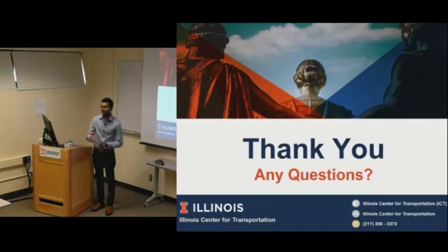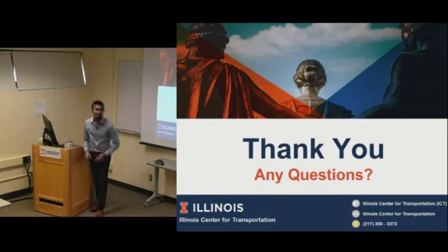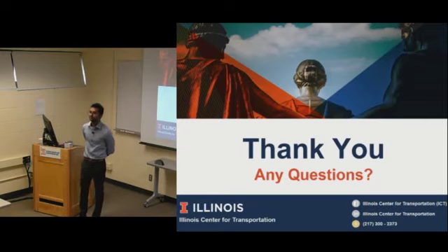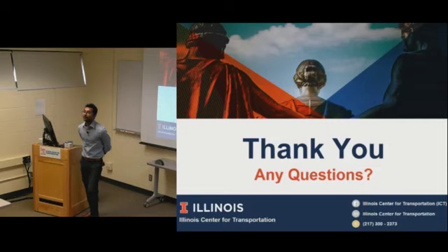Okay, Mike. Yeah. There was a slide, and you were, I think, comparing lab mixes. It indicated that the aggregate structure was the same, but changing the percent of ABR. I guess with that ABR, you're also introducing that aggregate portion from RAP. Is there any chance that there's a significant enough difference in the aggregates coming from RAP that it could influence your performance? Yes, that's possible, and that's where the ABR content was kept low up to 20%.